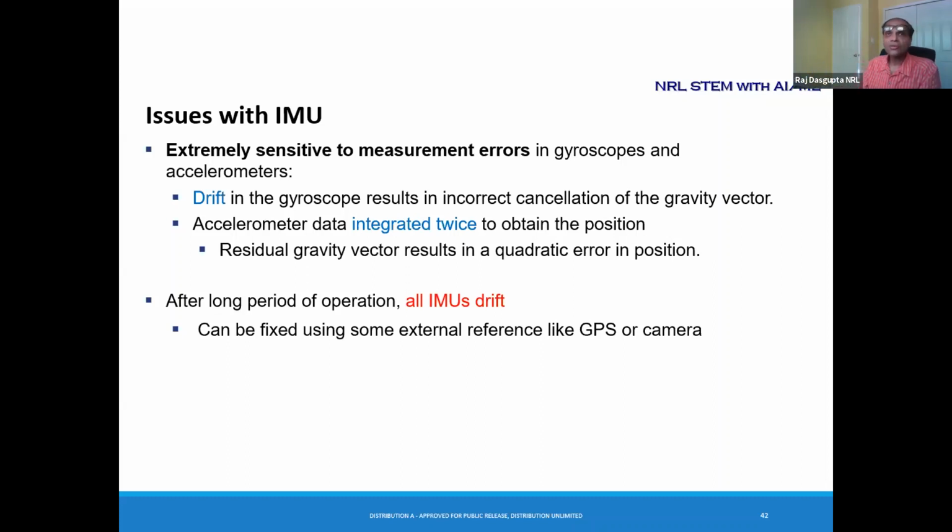So along with the IMU, you need to use a software component called a filter. There are many filters available, and a very commonly used one is the Kalman filter. In very layman's terms, a filter looks at the past values that the sensor has accrued, and smooths the current reading over the past readings.